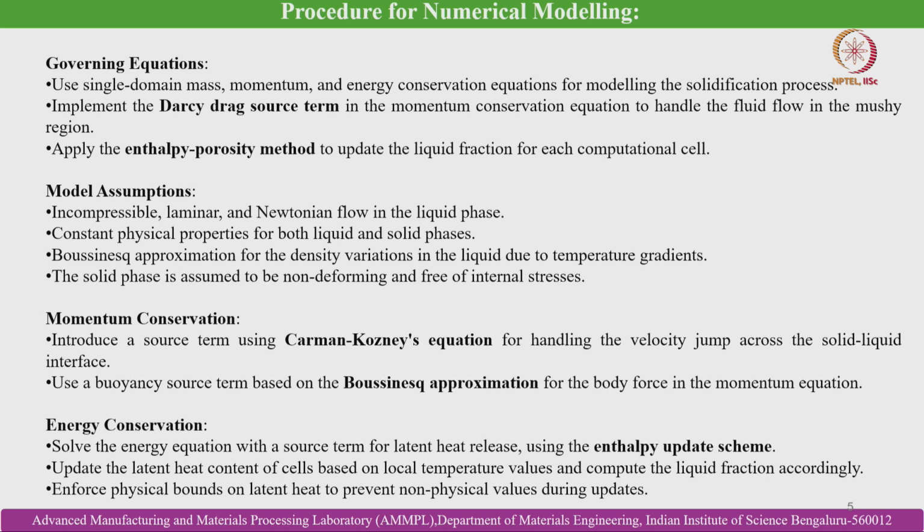that exist during solidification. A simple understanding of temperature gradient, like we have discussed earlier when we were discussing casting: because solidification starts from the wall, the solidifying dendrites or cellular structure grows in the direction opposite to the heat removal, and there exists a thermal gradient. So assume this is the solid liquid interface.